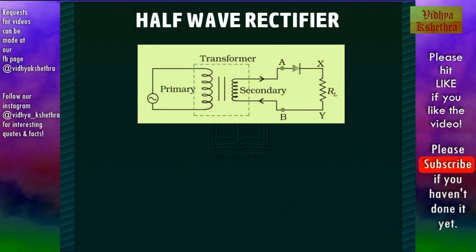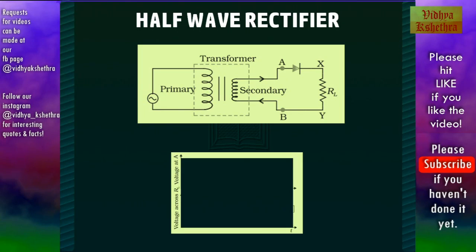The diode gets forward biased when the voltage at A is positive, and it gets reverse biased when the voltage at A is negative. When it gets forward biased, it allows the flow of current and we get an output across the load resistor R. Now we can see the input voltage and output voltage.